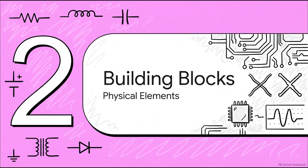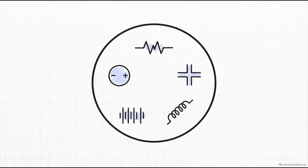Section 2. Building blocks. Now, a network can contain a bunch of different elements, but let's quickly run through the 5 heavy hitters. First up, the resistor. It acts like a bottleneck, opposing the current and turning electrical energy mostly into heat, which is dictated by good old V equals IR. Next, the capacitor. Super important for filters and timing because it temporarily stores energy in an electric field. That's I equals C dV/dt. Then the inductor, doing something similar but storing energy in a magnetic field, where V equals L di/dt.